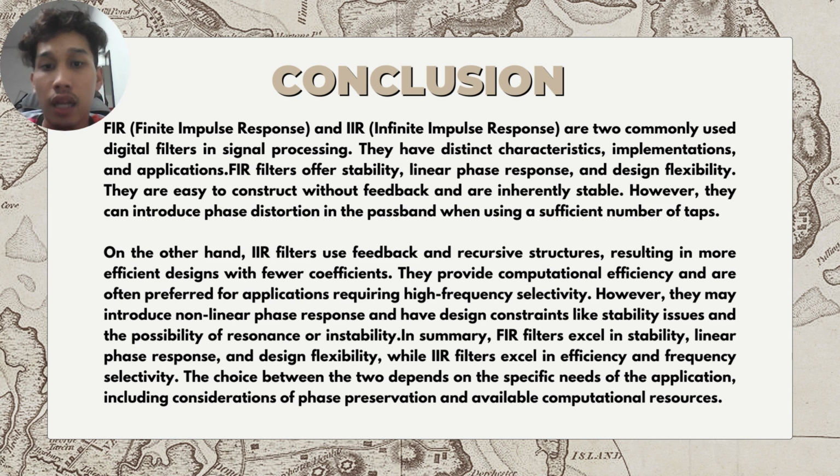On the other hand, IIR filters use feedback and recursive structures, resulting in a more efficient design with fewer coefficients. They provide computational efficiency and are often preferred for applications requiring high frequency selectivity. However, they may introduce nonlinear phase response and have design constraints like stability issues and the possibility of instability. In summary, FIR filters excel in stability, linear phase response, and design flexibility, while IIR filters excel in efficiency